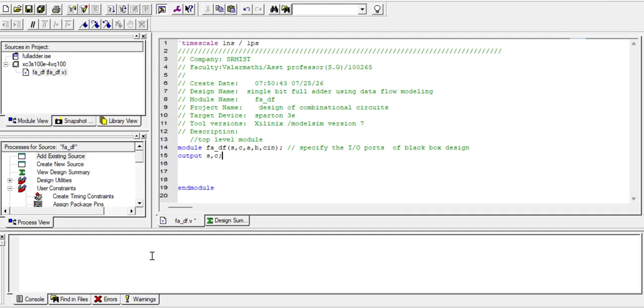If you type that wrongly, then you will not get the proper output. So that is a logical error, a logical error done by you only. Fundamentally, you have to be very strong in what a full adder is, what the full adder truth table is, what the full adder Boolean expression is, how they are implemented using gates, and the black box, how you define the inputs and outputs. That is a fundamental concept, you have to be very thorough.